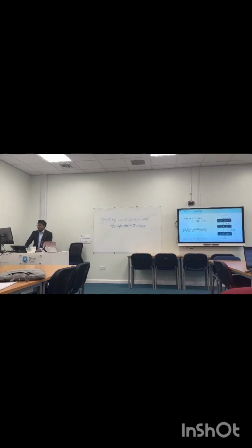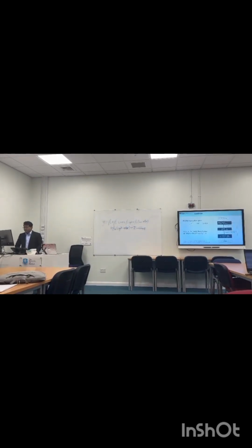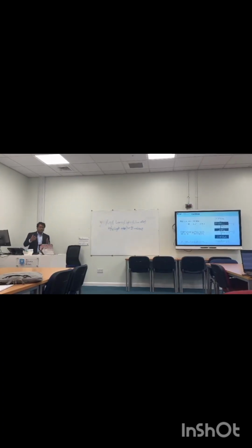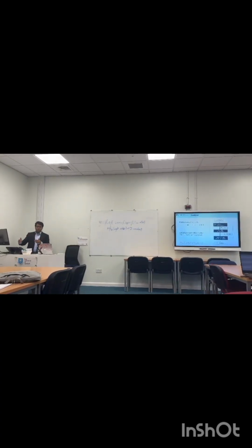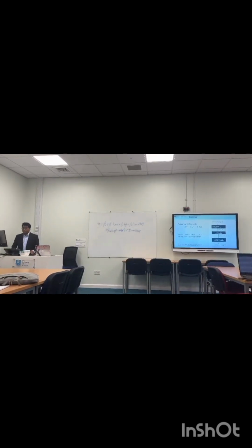As I said, PLL has mainly three parts. One is the phase detector, which means the difference of angles, what is the angle difference between two signals, like phase 1, phase 2. Then there is a loop filter, which is mainly a PI controller, and a voltage controlled oscillator.